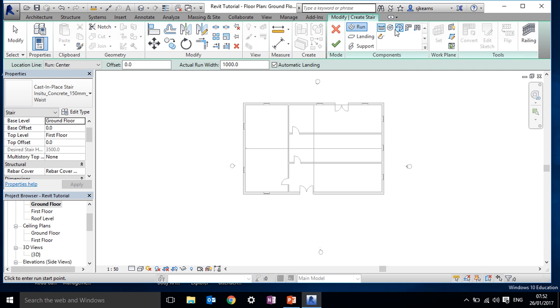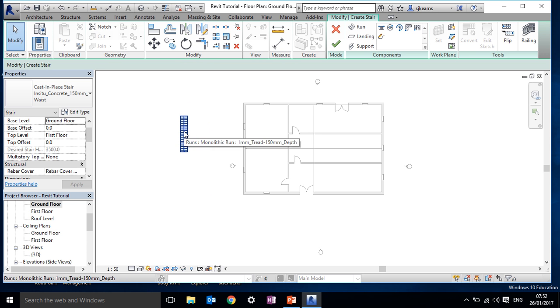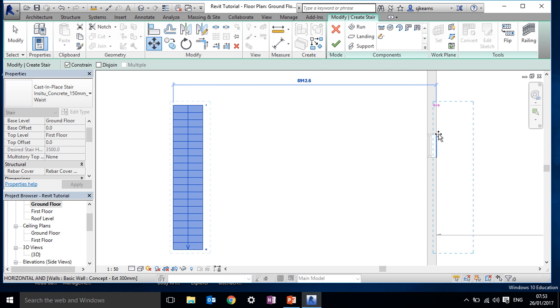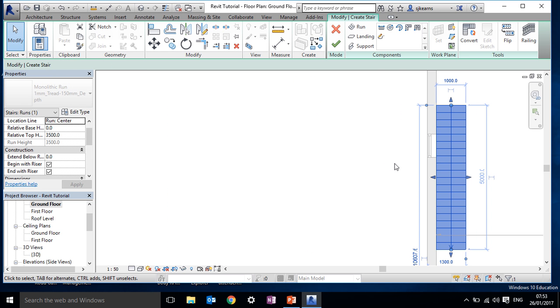So I'm going to draw a straight staircase. Okay, it's important to remember here when you've got a stairs that you've got enough room for the landing at both sides, so that actually you're not walking into a wall. So I'm just going to draw that there and move it. So select the object, finish selection, select the endpoint, and then I can move that such that that's there.